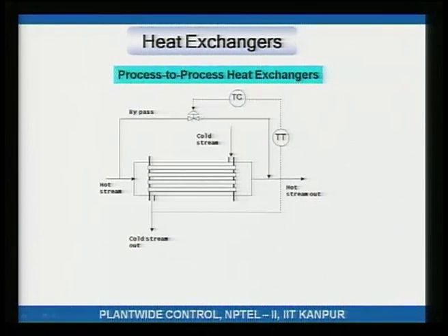Let us say you open the bypass valve. What that means is less hot stream is flowing through the tubes. So, less heat flows through the tubes. Therefore, the tubes will get less hot, and because the tubes are getting less hot, the cold stream will get less heat, and because the cold stream is getting less heat, this cold stream will become hotter or colder? Because the cold stream is gaining less heat, it will become colder.